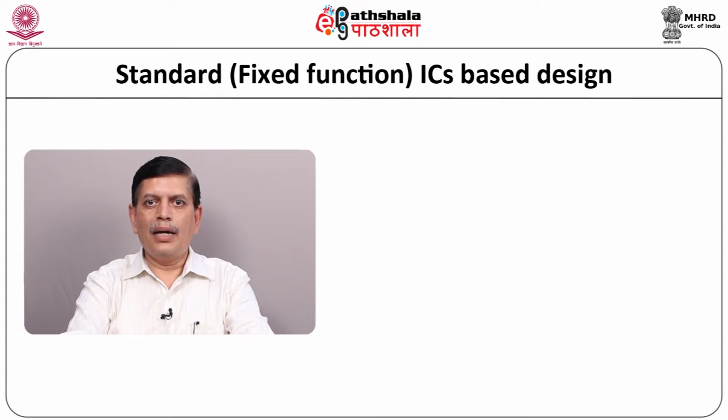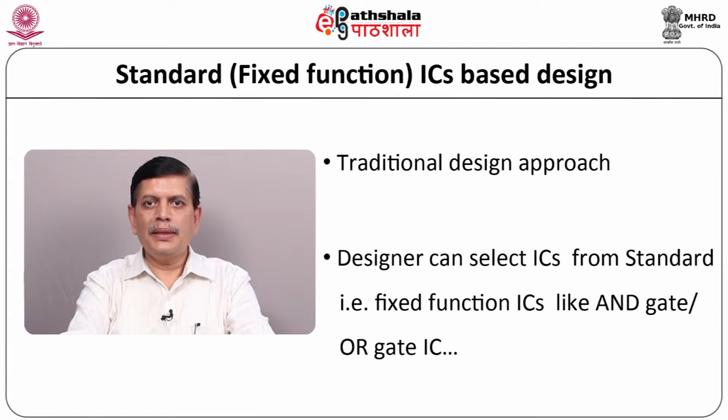This is a standard design approach which is usually called the traditional design approach. In this system, the designer selects ICs from available standard function logic families. For example, we have TTL, ECL and CMOS logic families, and the designers have a choice to select one of them. Mostly the ICs selected are fixed function ICs. The examples are AND gate, OR gate, NAND gate, NOR gate and so on. You can have even complex ICs like multiplexers, demultiplexers, encoders and decoders which are normally used in such a design approach.